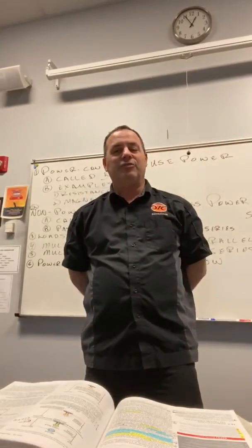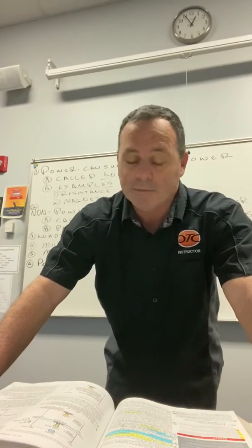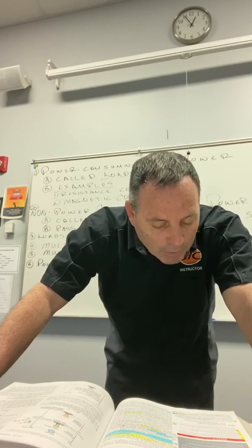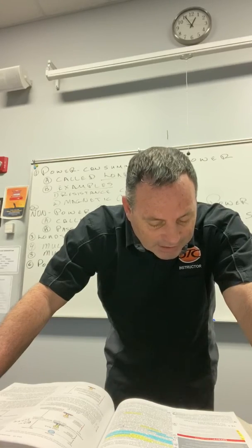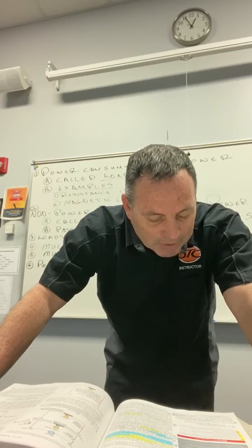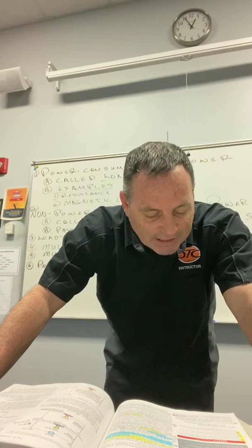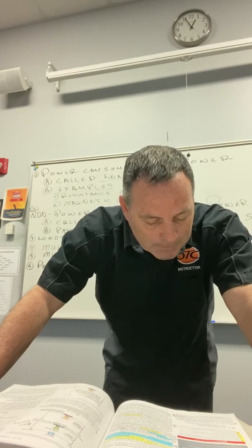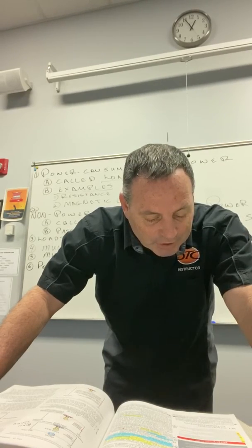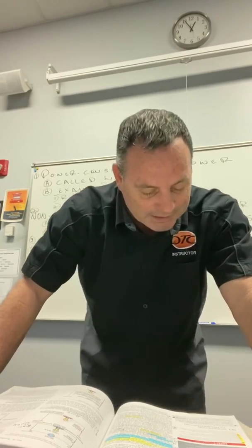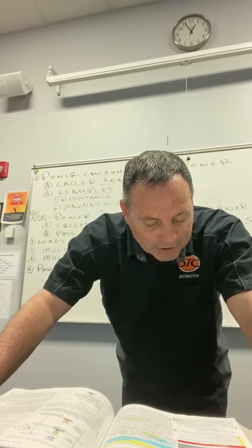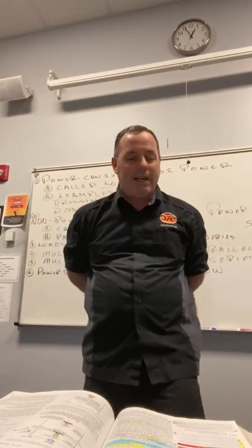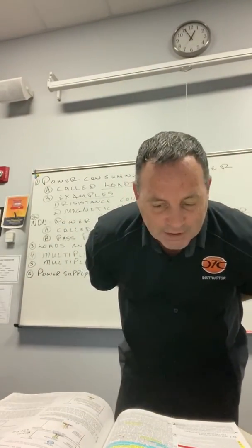All right, so the first thing it says is introduction. It's a good place to start. Each control must be evaluated to its function, major or minor. Recognizing the control and its purpose requires understanding its use in the system. Studying the purpose of a control before you take action will save a great deal of troubleshooting. So look for pressure lines going to give pressure controls and temperature activated for temperature controls and determine what it is.